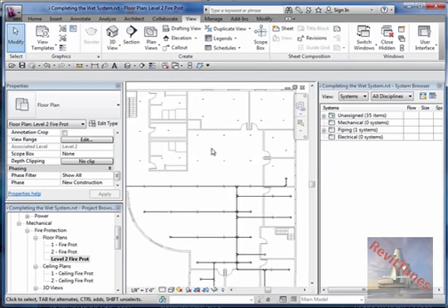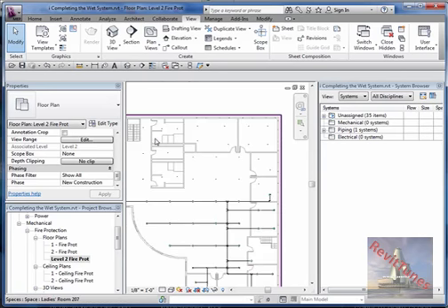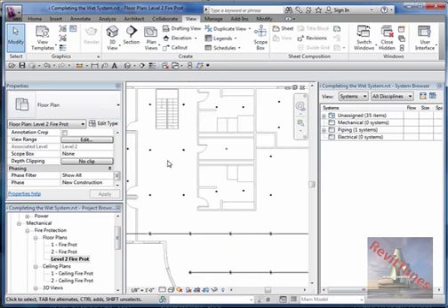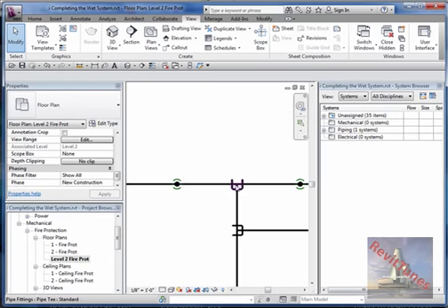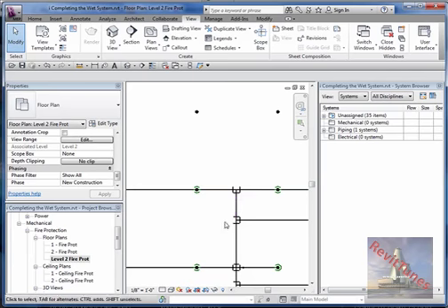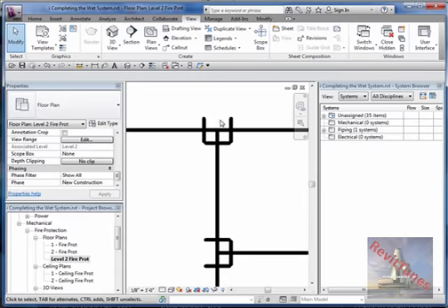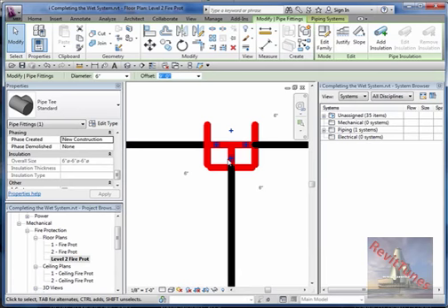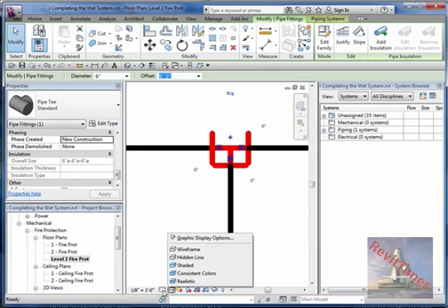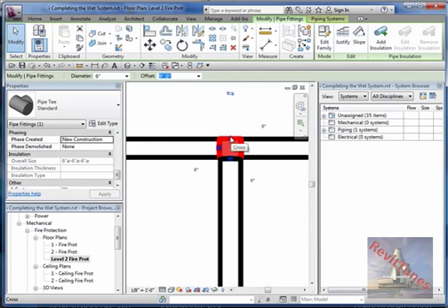Okay, now we are going to incorporate these fire sprinklers from the other half of the building that we didn't do before. To do that, first, this is the main pipe. This is the main line. If I touch this, I will see a plus sign. Sometimes I prefer to see it in 3D. If I go to detail mode here, I see it in 3D. And if I touch the connector, I see the plus sign here.